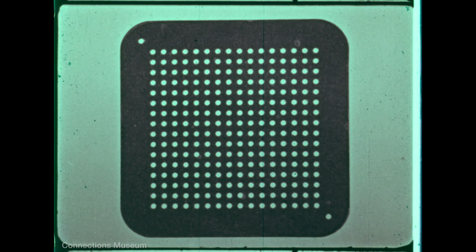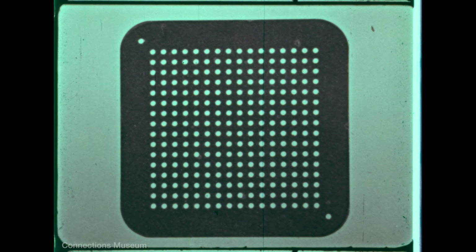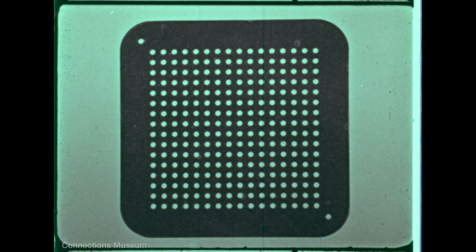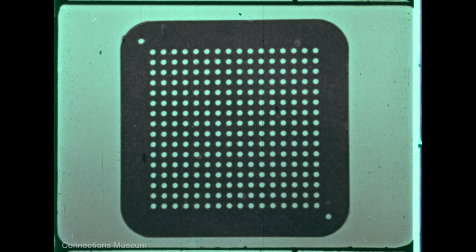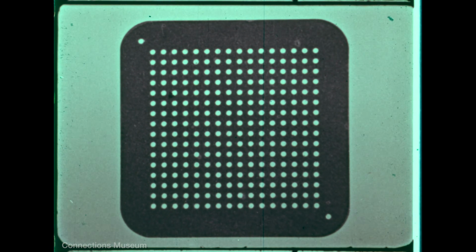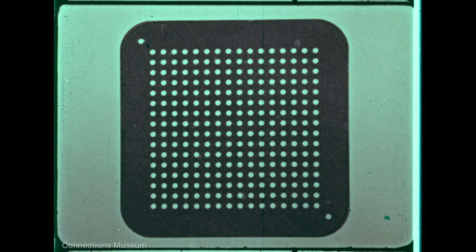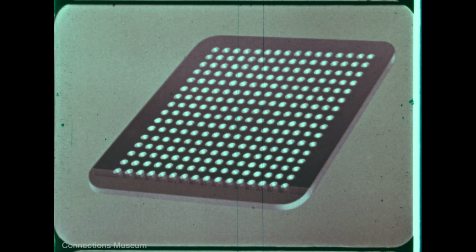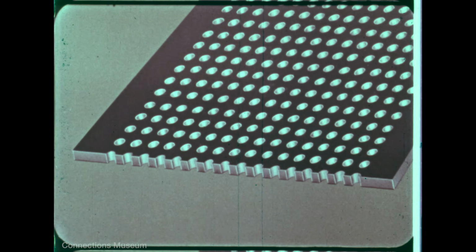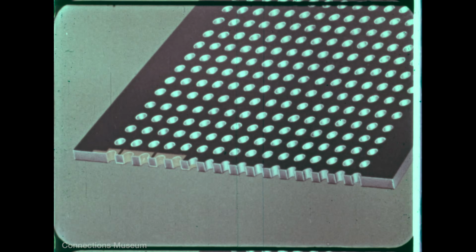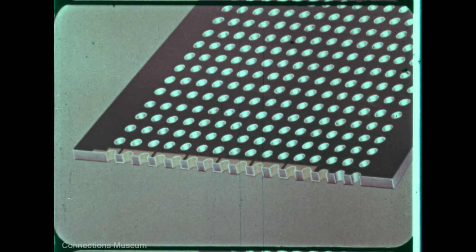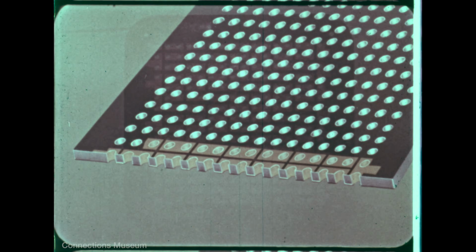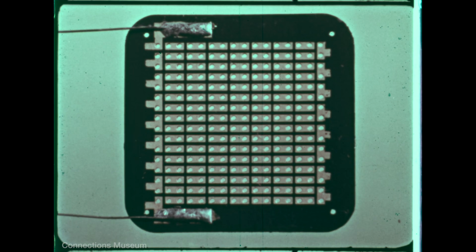The ferrite sheet memory uses the same magnetism principle as the core array. In this thin sheet of ferrite, the areas immediately surrounding the small holes act as cores and store bits by being magnetized in one of 2 directions. One long conductor is electroplated onto the sheet, lacing in and out of the 16 by 16 array of holes. This is the Y wire.